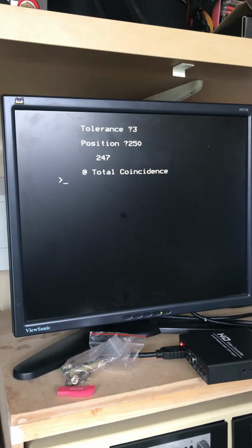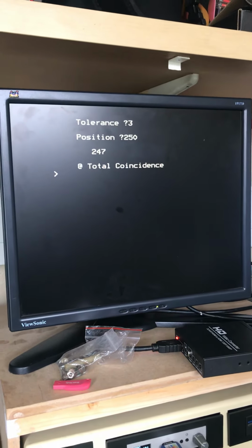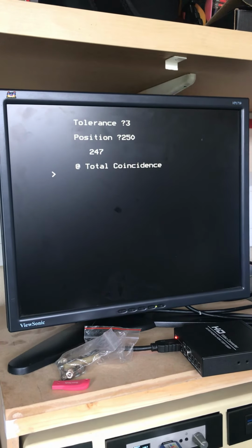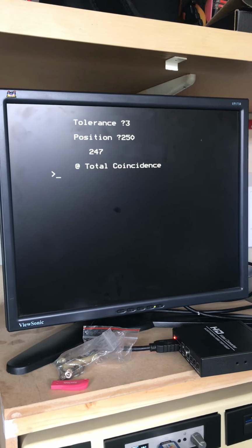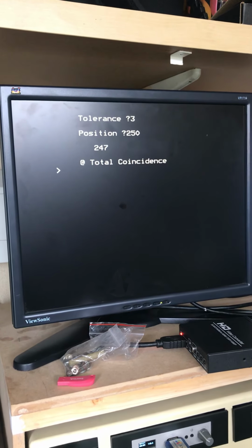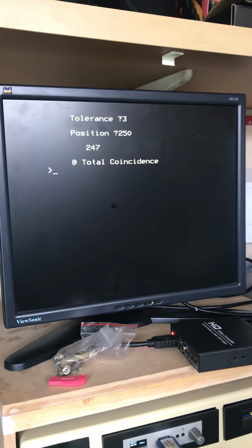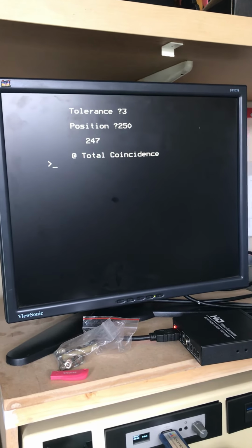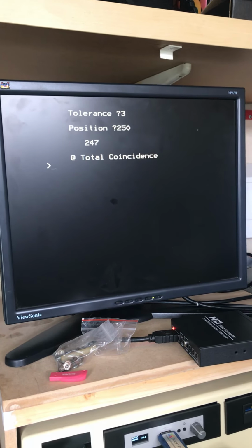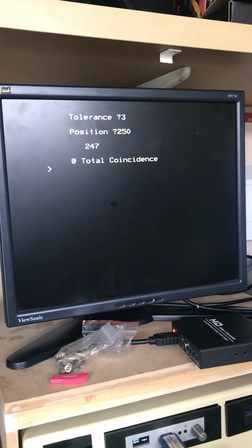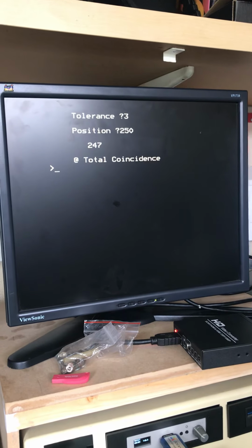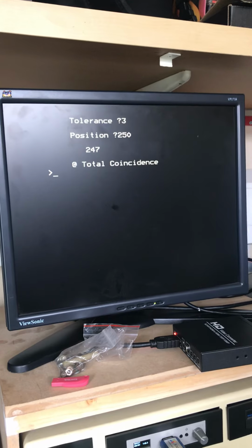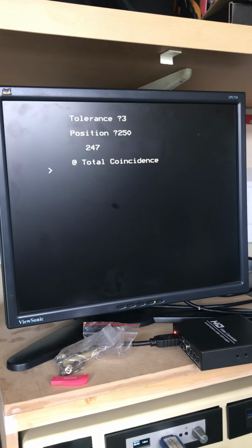So that's working. What I've now got to do is calibrate those pots properly to get them really accurate. There are all manner of other things to consider here, because there's backlash in the gears, and it's not that accurate anyway. So if I can get tolerance within plus or minus 1, I'd be happy. Well, I'll be happy with plus or minus 2 actually, but 3 might be a bit dodgy. It's not quite right, so we'll see how it goes.